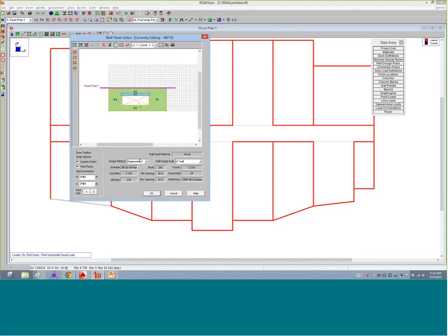So we're going to see we have kind of different options once we look at solution, but all of that is based on whether I choose design method, segmented, perforated, or force transfer around openings. If you don't have any openings, then it's going to be a segmented wall. If you do have openings, you can make some choices here. So let's first of all, this first wall, we'll use it as segmented.